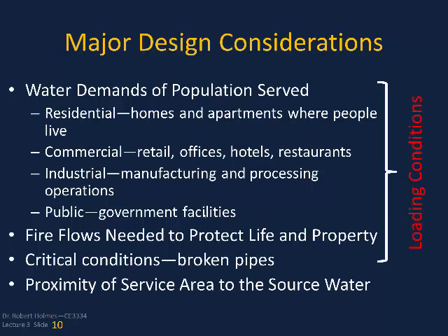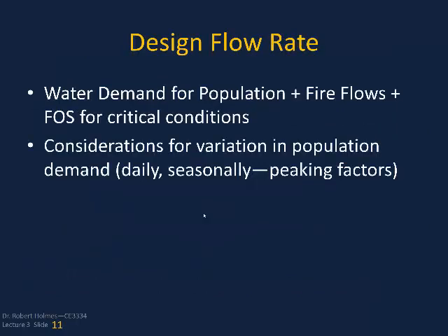And then you've got some critical conditions such as broken pipes. So we have to add in a factor of safety. The last thing that we need to be thinking about is the proximity of our water distribution service area to the source water. Are we going to have to pump this from miles and miles away to get it to the treatment plant and then out to the distribution system, or is the source very close, such as groundwater wells like we have in the city of Rolla?